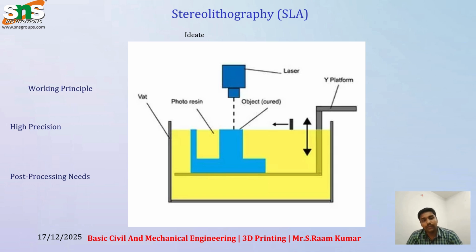This is how stereolithography works. It is most suitable for producing high precision products, such as jewelry casting. To develop highly accurate, complicated structures, we can go for SLA. Compared to FDM, which can produce the most viable, most available components, SLA has the capacity to develop products with a glassy finish.